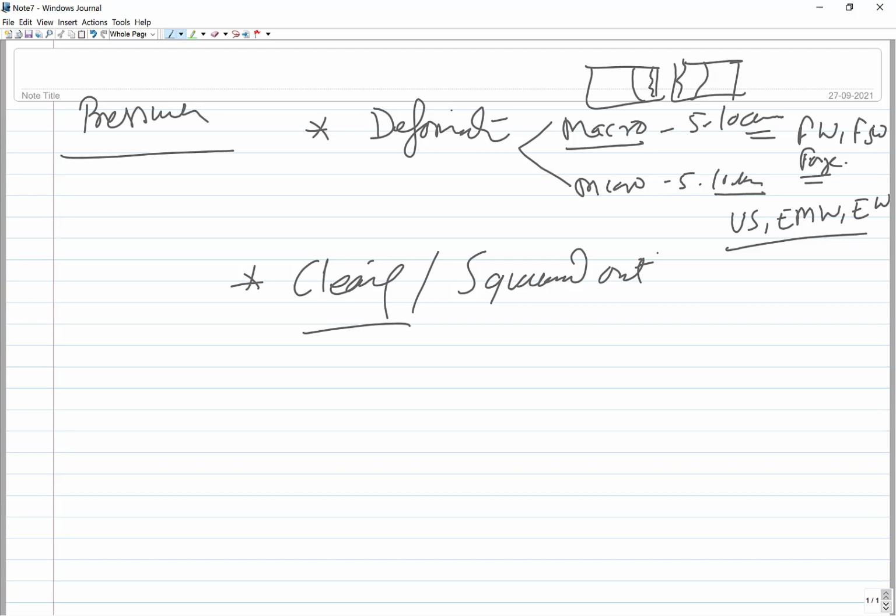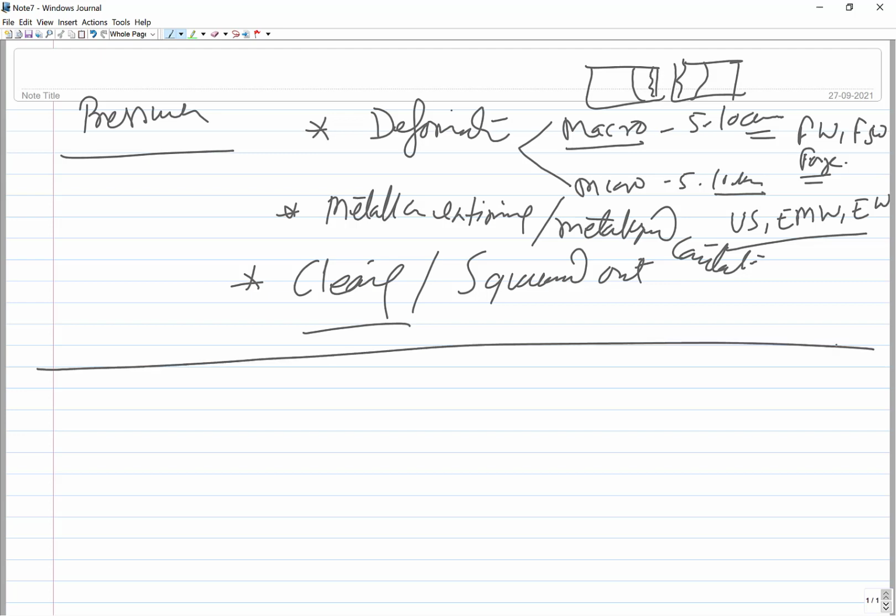These are the two things which are realized, and whenever there is a deformation, it helps to improve the metallic intimacy, metallic closeness, or metallurgical contact between the two, which is established for facilitating diffusion across the interface. So this is about the role of pressure.